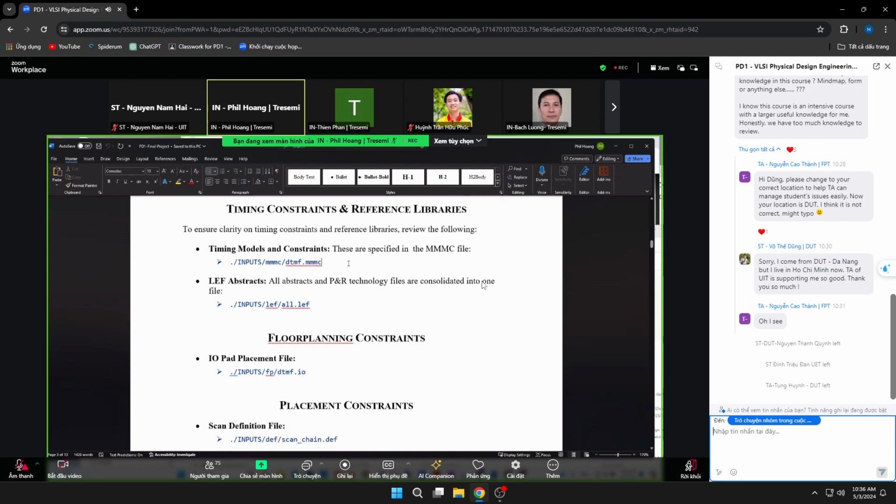RC corners in there, and you have the timing constraint SDC, and you have analysis views that you have for active analysis in setup and hold. And then you have the physical views. In this case, in the lab, you have a technology LEF and you have all the cell LEF.